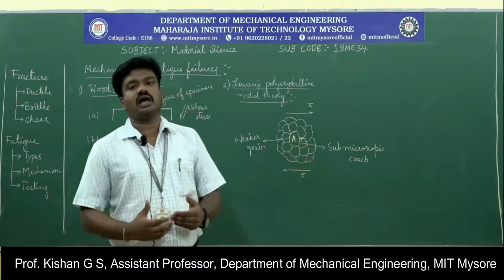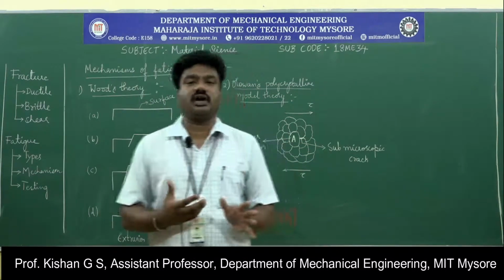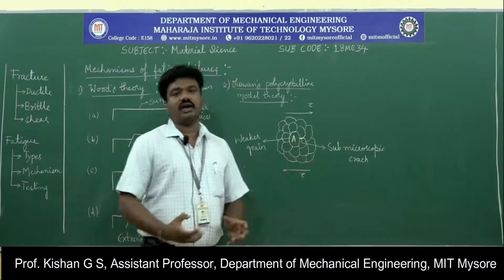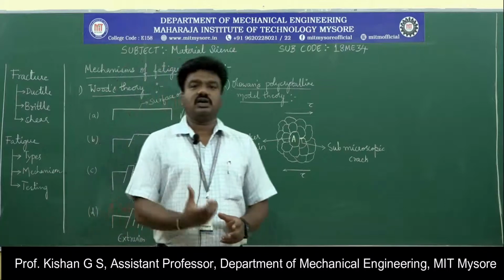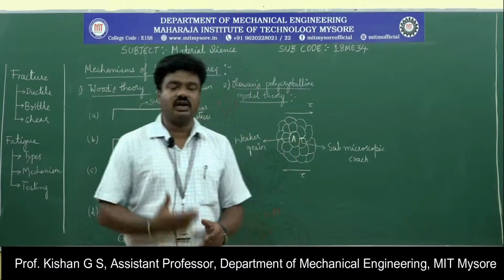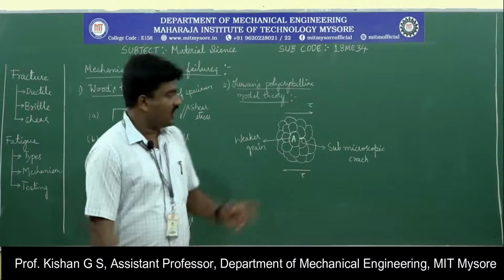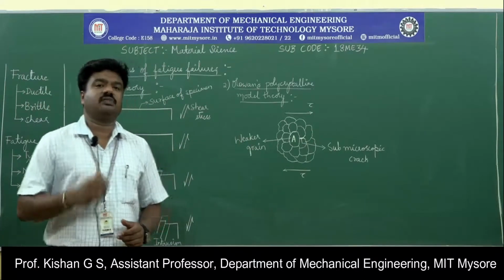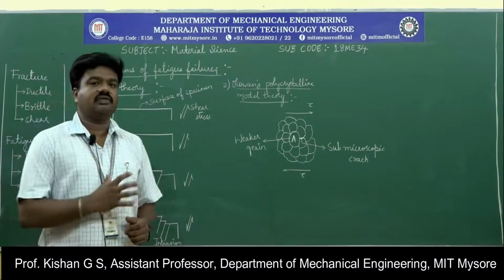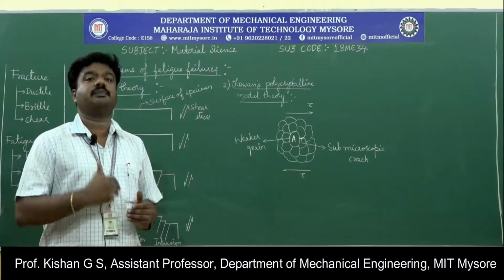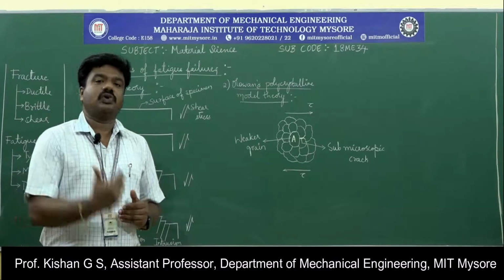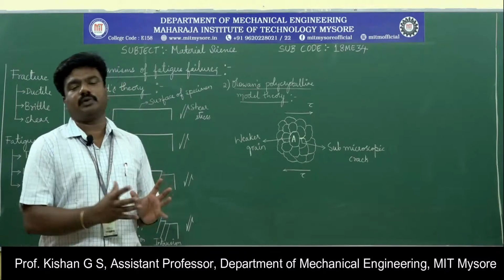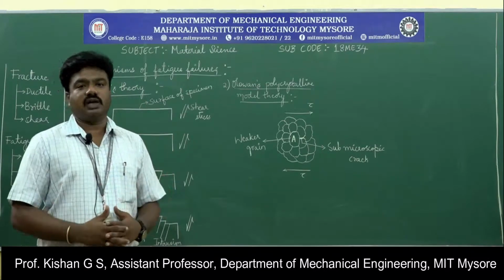So progressively, when the same type of alternate loading condition is repeated, this submicroscopic crack leads to a crack, and that leads to a cavity, resulting in the fracture of the material over a period of time. So here both theories represent the failure of a material when it is subjected to alternating loading conditions repeatedly over a period of time. That leads to progressive fracture, which in general we can consider the entire process to be under the fatigue behavior.